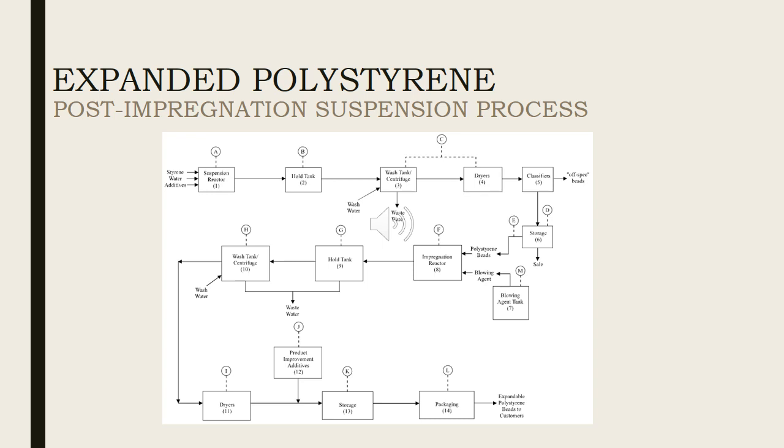An inert gas, nitrogen, is frequently used as a blanketing agent in order to maintain a positive pressure during the cycle to prevent air leaks. Once polymerization starts, temperature control is typically maintained through a water-cooled jacket around the reactor and is facilitated by the added heat capacity of the water in the reactor.